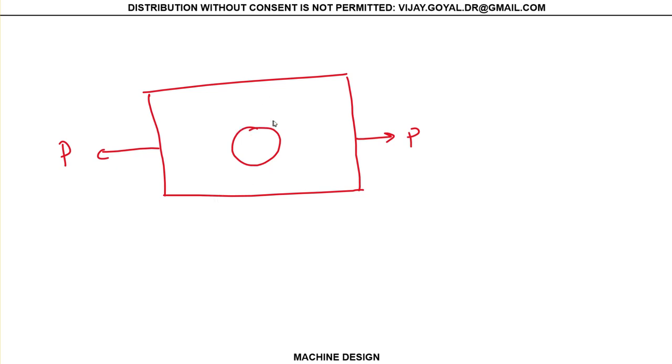What happens here is that because it's a ductile material, it has enough energy to redistribute the loads. So the flow pattern does something like this and continues. It does not create spikes. There are absolutely no spikes created in this model because it's a ductile material. If it was a brittle material, the behavior would have been very different, and it creates sharp stresses.